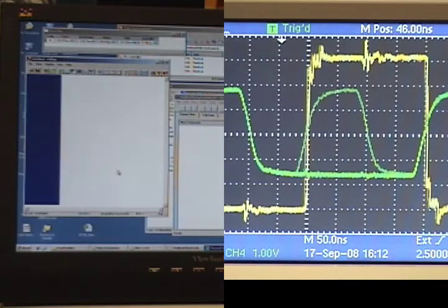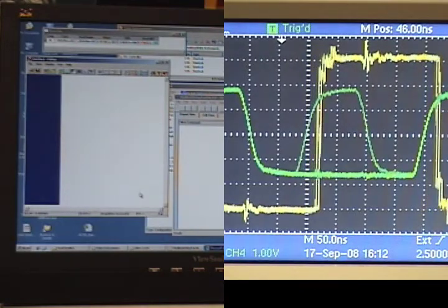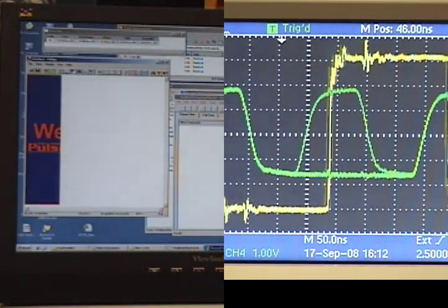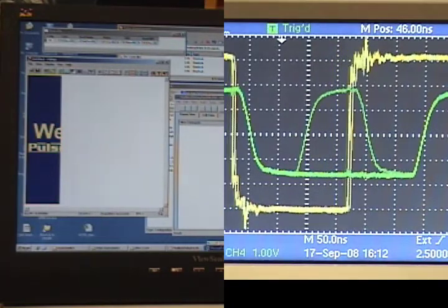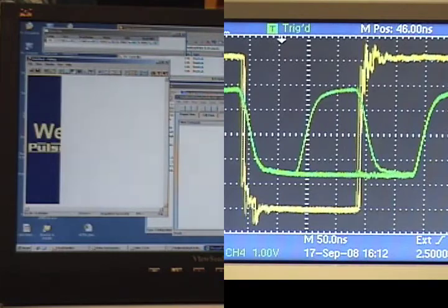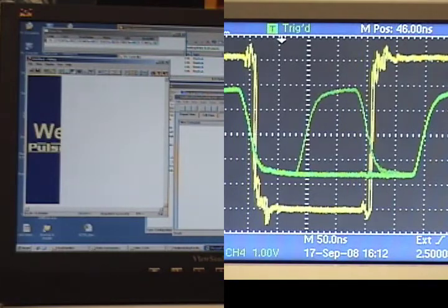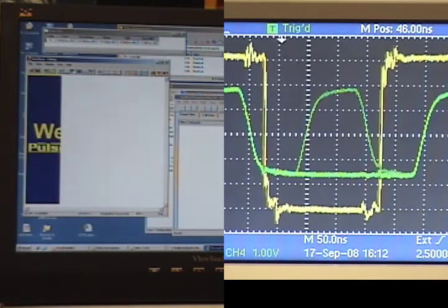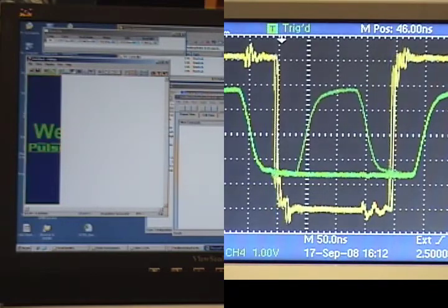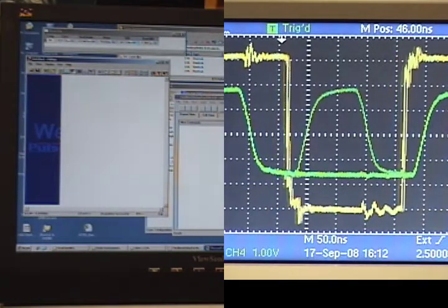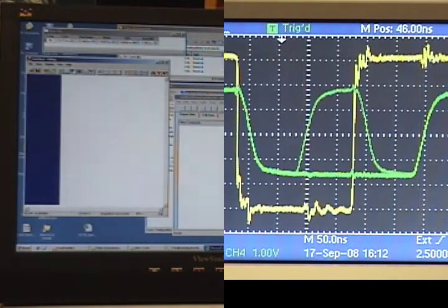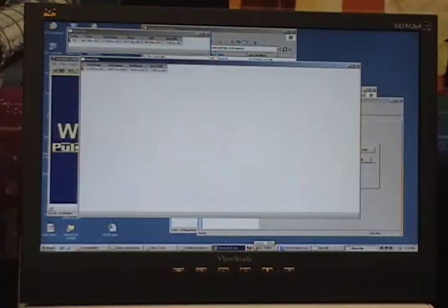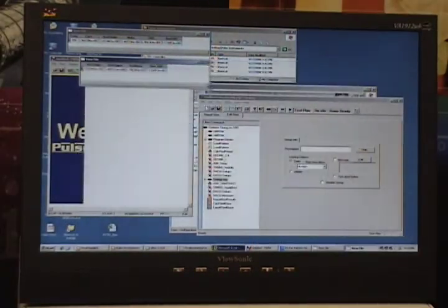This type of parametric sweep can be done for integration time, illumination level, wavelength, black body temperature, bias voltage, clock rise time, etc. This enables a tremendous amount of flexibility in characterizing device performance across a wide range of operating conditions and parameters. Best of all, once the test plan has been set up, you can click Go, have lunch, and return to the system once the data has all been collected and assembled into a report.